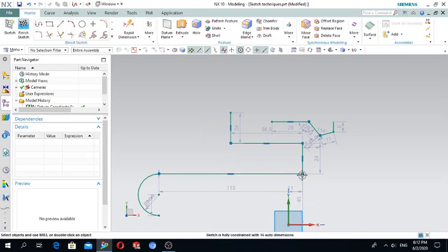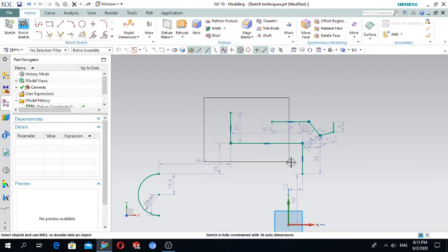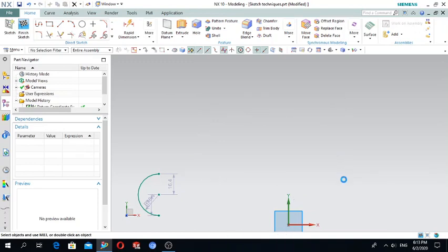To delete the created lines, select them and press the Delete key on the keyboard. To select more than one line, click multiple line segments and the lines will be highlighted. You can also select multiple lines by dragging a box from left to right. The lines are highlighted, selected, and then press Delete. So also delete this arc. So this is about the arc command.